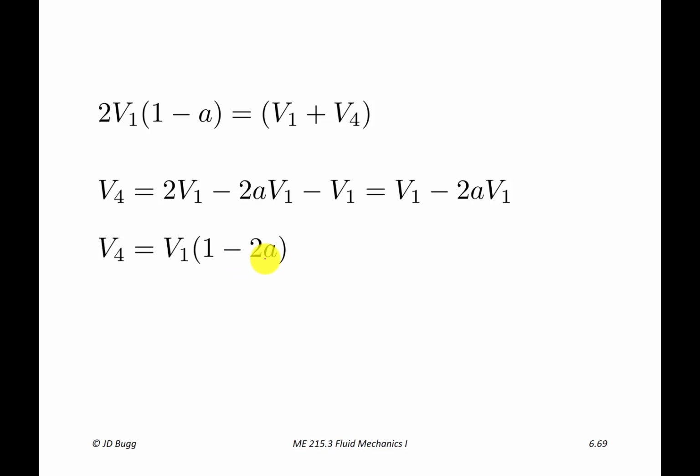So remember, when we defined the axial induction factor, it told us something about v2 relative to v1. Now we've looked at these conservation laws, and they're telling us something about v4 relative to v1. And they're telling us something interesting. So here's what we got for v2. So v4 equals v1 times (1 minus 2a), fine. v2 is v1 times (1 minus a).